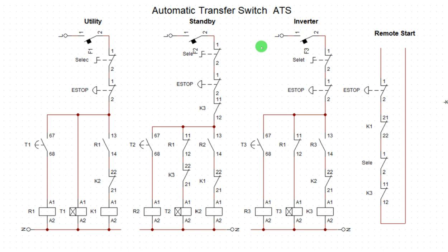Okay, now I want you to pay attention again. The cooldown duration for the genset to cool down before shutting down. Every digital genset comes with that feature. So don't bother putting it again so that I will not complicate or make your logic complex. So take away that shutdown logic. Don't put another timer. The genset will have it.